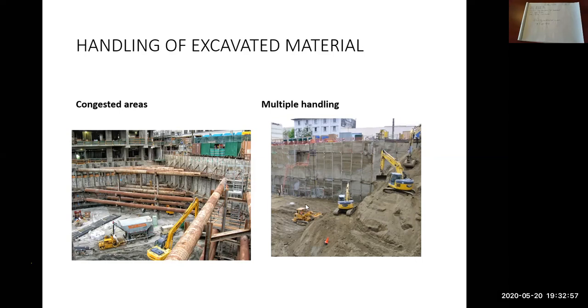So you can see this would be a relatively expensive excavation. You're still only doing 20 cubic meters an hour, maybe less, but you have 4 machines here doing that volume. Maybe it's even less than that. Maybe it's 15 cubic meters an hour. So instead of 1 machine, you have 4. Maybe there's multiple dozers in the bottom as well. So again, it really depends on how big this excavation is.